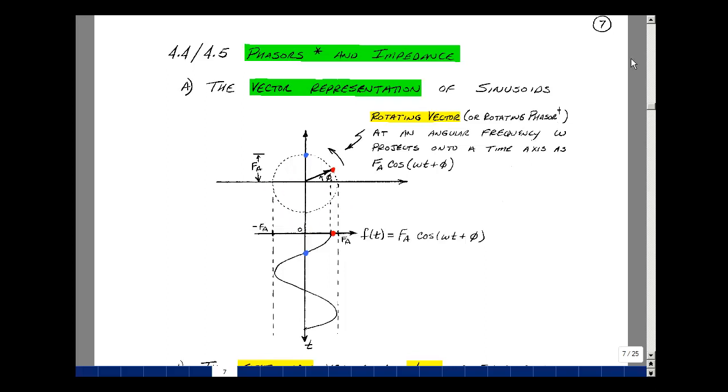A sort of merry-go-round exists on which all of the vectors are riding. This merry-go-round is called the frequency domain. If one is in the frequency domain revolving with the vectors, they appear to stand still. Thus the amplitude and angle of voltages and currents can be captured by stationary vectors or phasors at t equals 0. Since all of the phasors in any given problem are on the same merry-go-round, they are stationary with respect